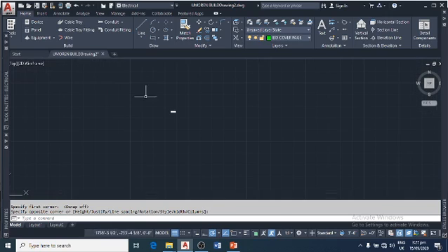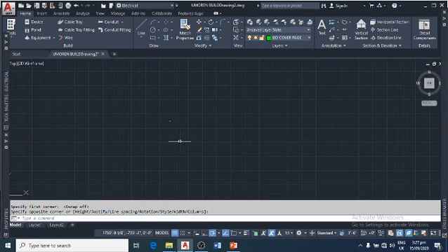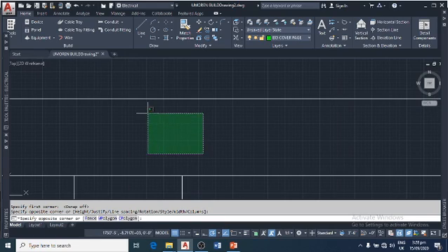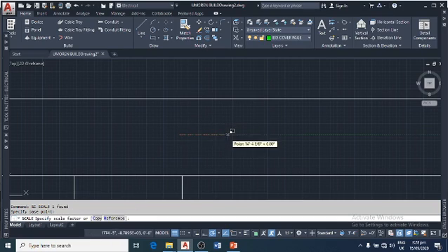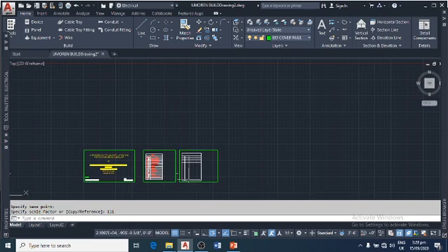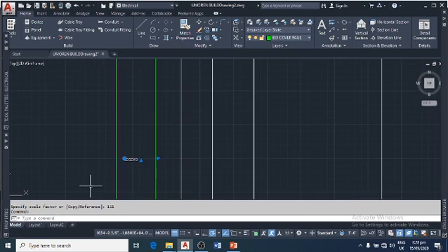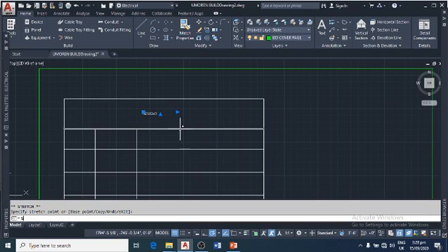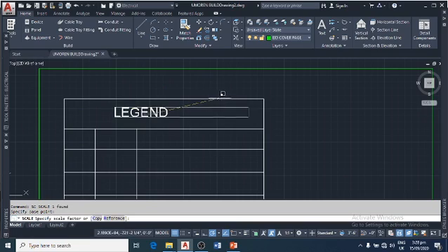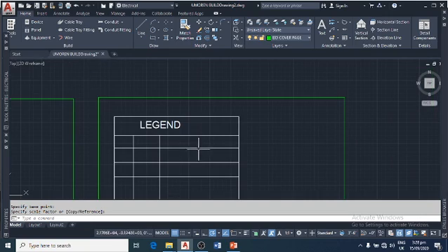That's the text, but it's quite small, so we have to scale it. I select the text, type S for scale, Enter. I click and scale the object. I think it's about right now, so I can move it to where I need it. Then I scale it again to the size I want. Okay, that's it. I have the legend.